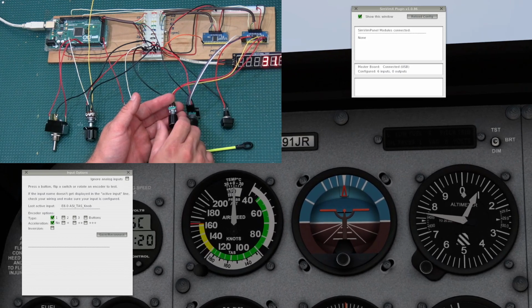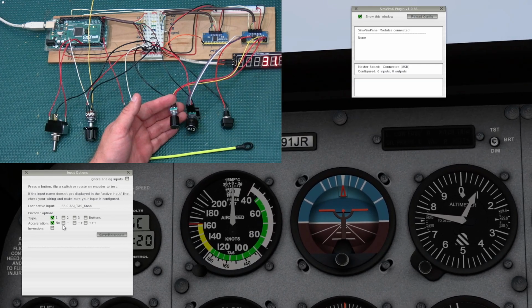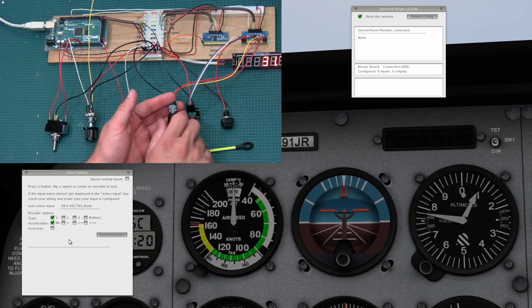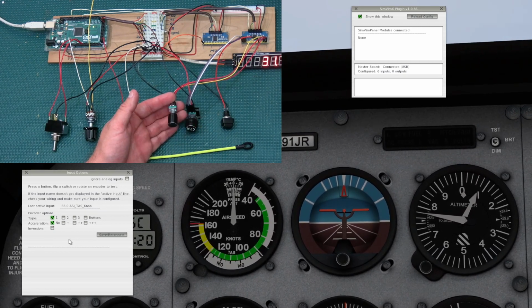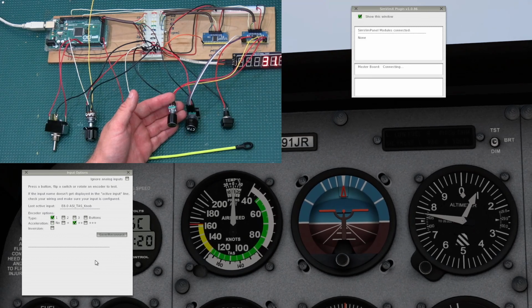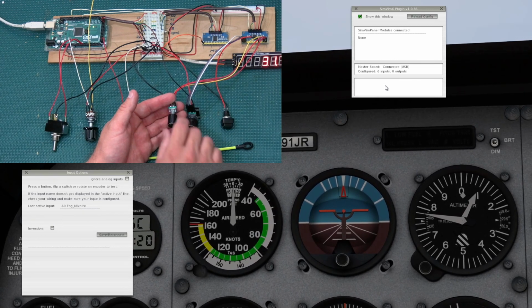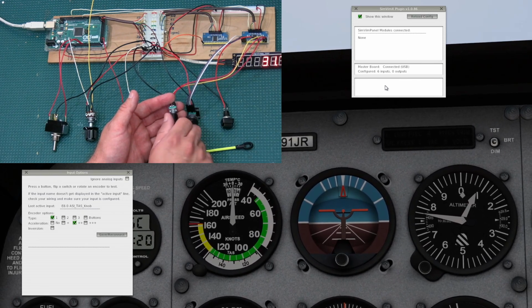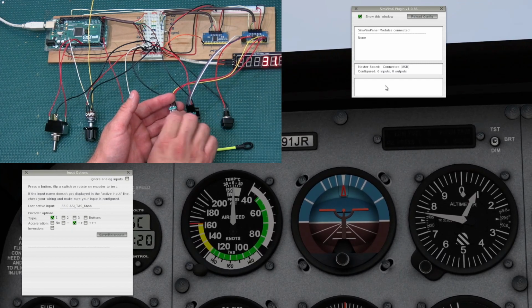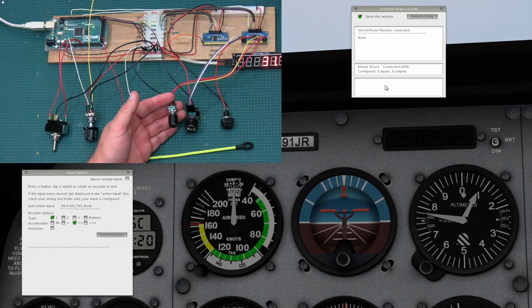And one more thing, you need to make sure that you put the correct type of encoder, and also if you want to put some speed, because right now you can see that it takes forever to move through here, right? But if I put a lot of speed and then I save and reconnect, you have to wait, of course, until it's connected again. So there, now we can do it, and you can see that it moves a lot faster if you move it fast. That's kind of cool that you can do that.